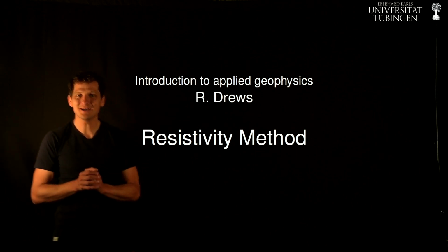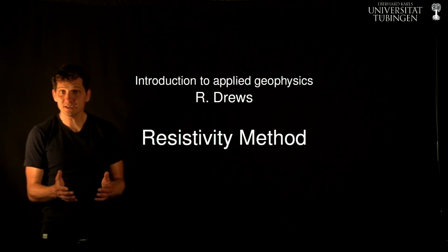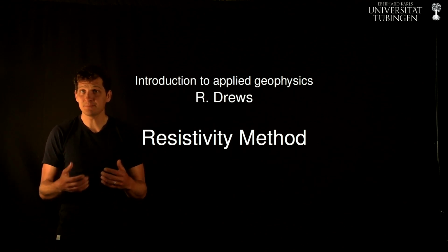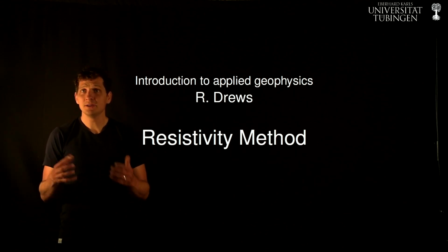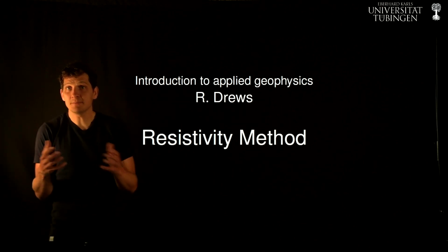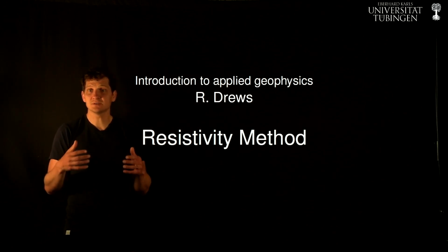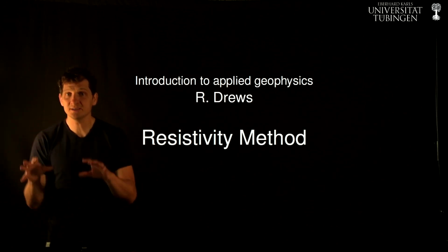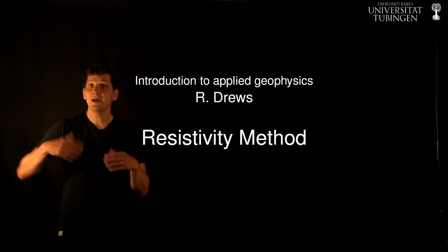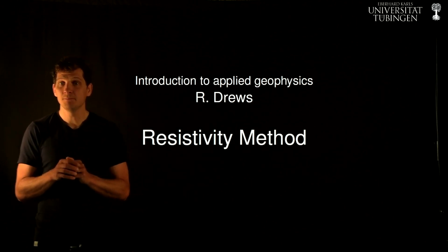Dear friends, welcome to a video introducing the resistivity method as a geophysical surveying technique that is predominantly used for the near subsurface, meaning typically a few tens of meters in depth. And this zone, which is sometimes also referred to as the critical zone, typically encompasses things such as the topsoil, the transitions of unsaturated and saturated depth intervals that go along with an aquifer if present, and it also contains a transition between weathered and unweathered bedrock material.